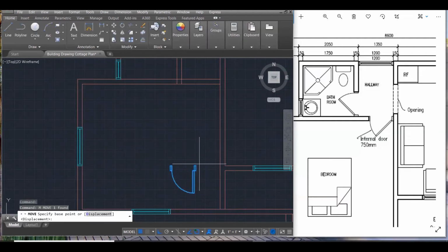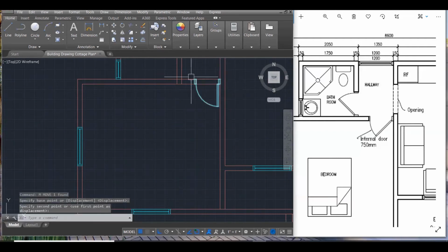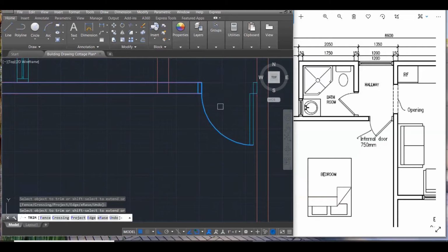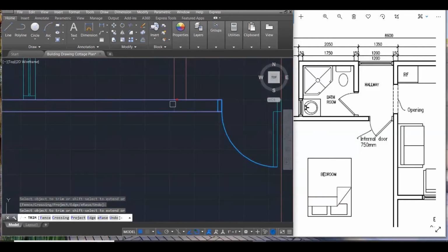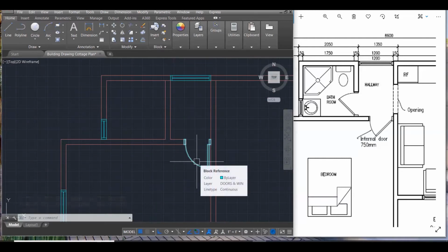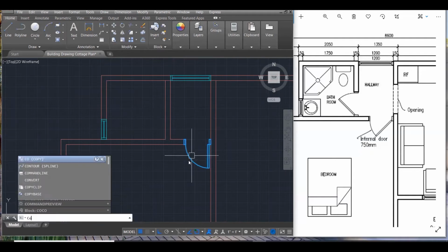And now I'm going to insert this. When I insert this, then I'll clean up the wall opening right here. So I can trim in here now so that we can access our room. Remove, remove. I can also trim these little points here while I'm at it. Then next, what I'm going to do is grab this door, rotate it. I might need to rotate it and then mirror it so that it goes into place to get into the bathroom. No problem. Copy it out first thing.